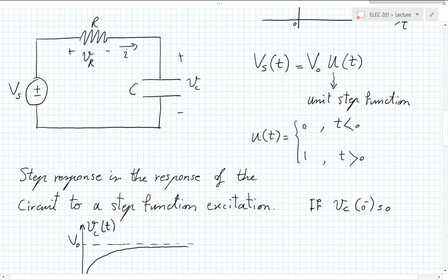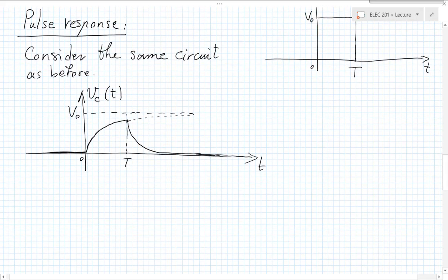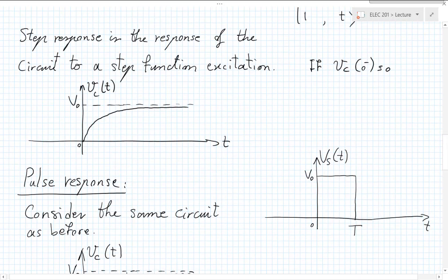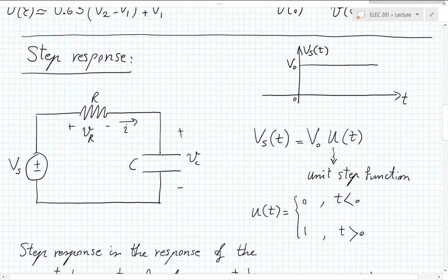Just after time t, what is the slope, positive or negative? Negative. The tangent to this, if you take that slope, that's negative. So immediately after time t, the current has changed not only its value, but also its direction. And so your I becomes negative immediately. And so the capacitor starts discharging into the resistor. And a sudden change in the current of the capacitor is not a problem.